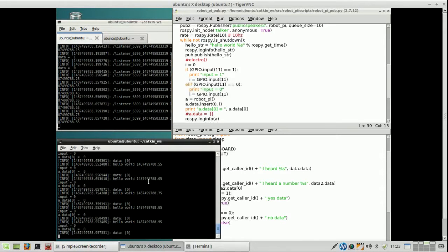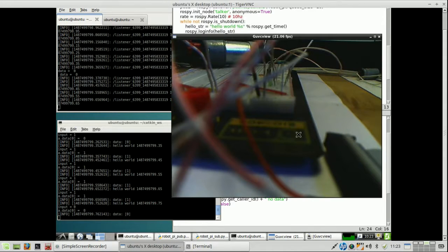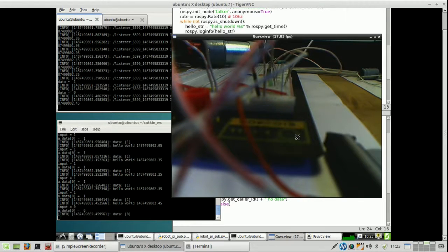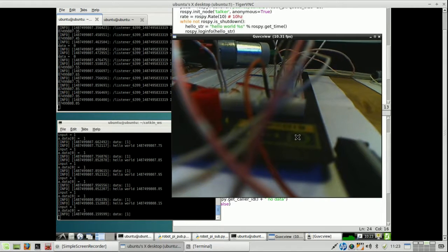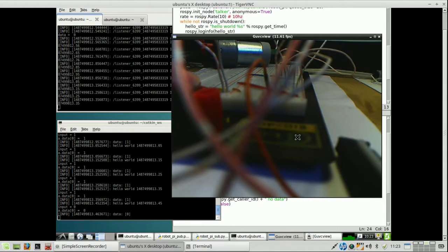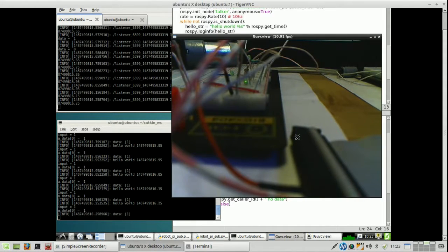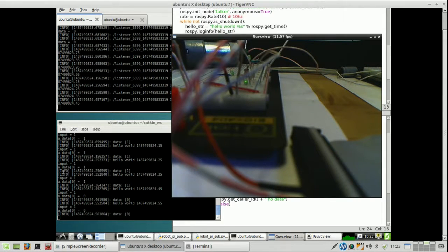And now it gives all zeros but also ones, and that is not correct, because, let me go back to the other one. Yes, if you see, I'm not pressing the switch now, and if I press the switch, the LED is burning, and yet you see zeros coming by still in this window, so something is still not correct.